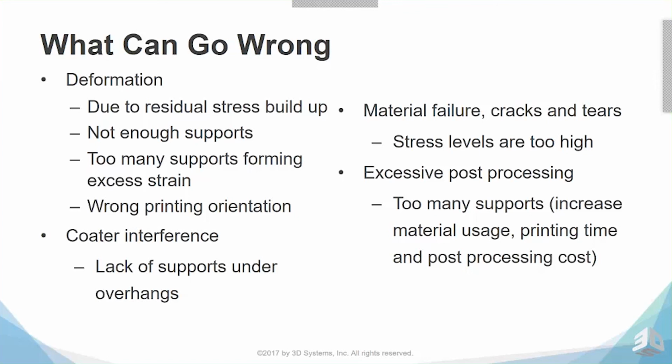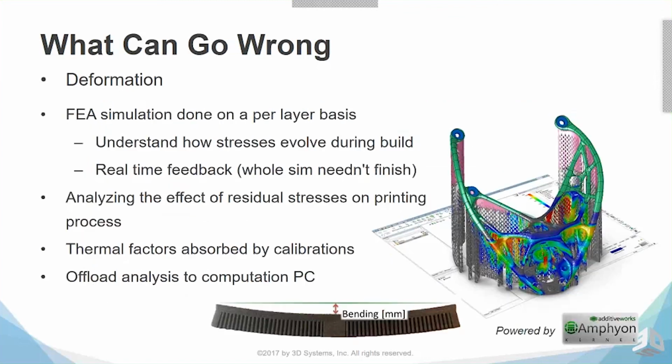And excessive post-processing. So maybe if you just have too many supports or supports in bad areas, they can be impossible to remove or just very time-consuming. And we definitely want to avoid that if we can.